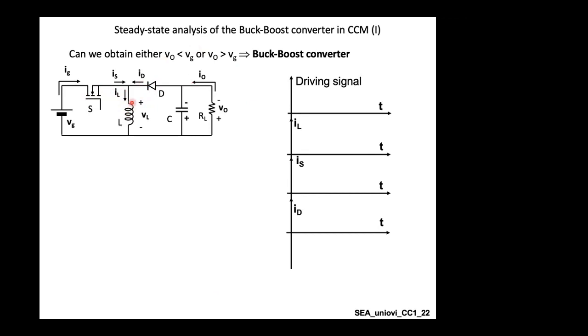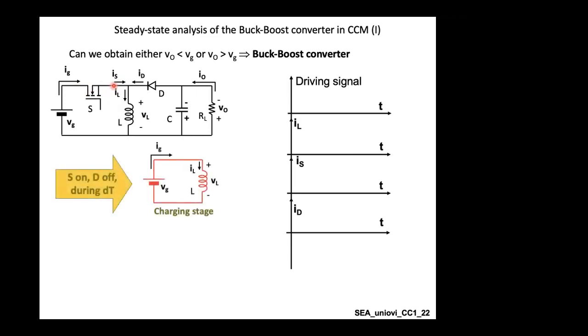So, as you can see, when you have a high signal here, which leads to a short circuit here, you will end up with something like that. This is simply because this diode will be in reverse bias, making this an open circuit. So you simply disconnect all these portions of the circuit, leaving only VG and a coil, which is quite the same as what we did with a boost converter, if you remember. So here the voltage in the coil is equal to the voltage of the generator, VG.